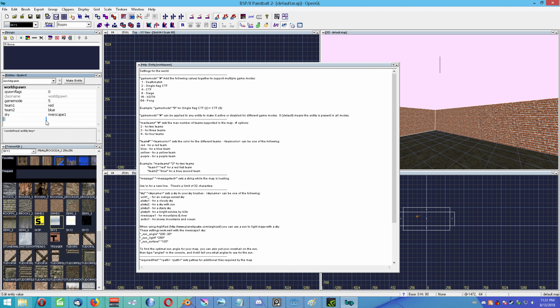And these are the parameters for sun lighting. We've got sun angle, which is the direction of the sun, 200, -30. Sunlight, that's the brightness of the sunlight, 250. Sun surface, that's the amount of light that comes from the sky in general. So that should be less light than the normal sun, but somewhat high for a daytime map.